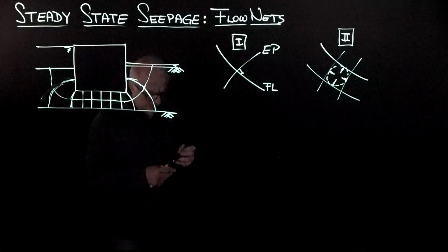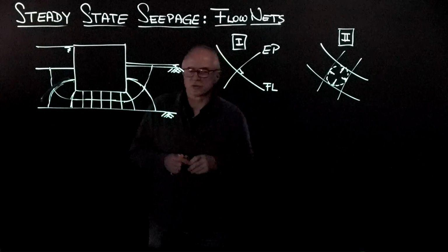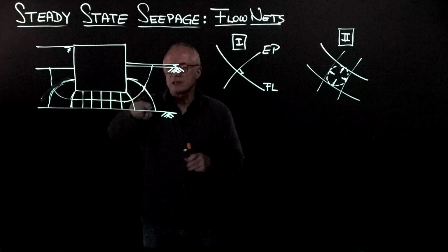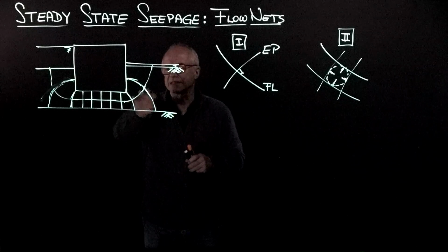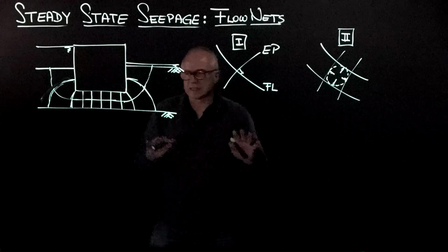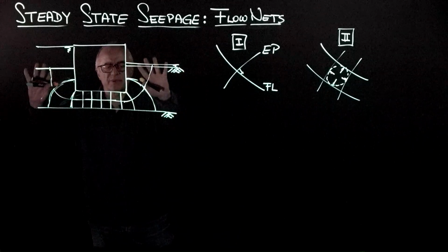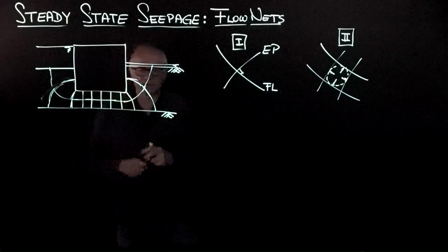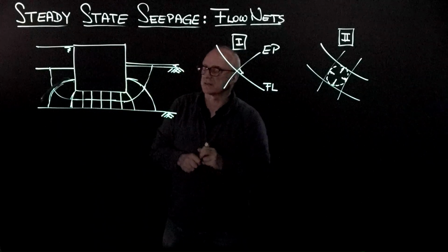Folks, it takes just a few minutes to sketch a reasonable flow net. And of course, if you try to fit a circle here, you realize that this is not properly accomplished. So the easiest way to proceed is to put a transparent paper and fine-tune on a transparent paper and keep doing layering until the system is resolved.